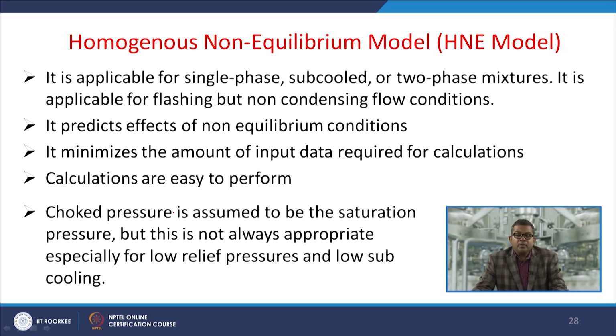So, it is applicable for single phase, subcooled or a two phase mixture. Now, it is applicable for flashing but non-condensing flow conditions. So, be particular about the use of this particular model. Now, it predicts the effect of non-equilibrium condition. Usually, it minimizes the amount of input data required for the calculation. Usually, calculations are extremely easy to perform.